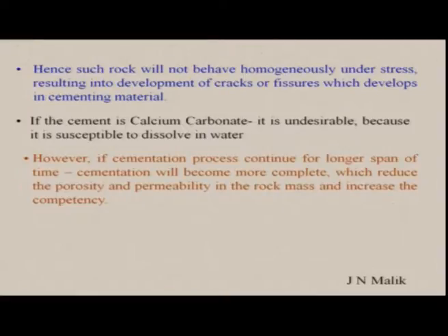However, if the cementation process continues for a longer span of time, cementation will become more complete, which reduces the porosity and permeability in the rock mass and increases the competency. That is, the strength of the rock will increase. So if the process of cementation and compaction lasts for a longer period, then you will have better rock strength.